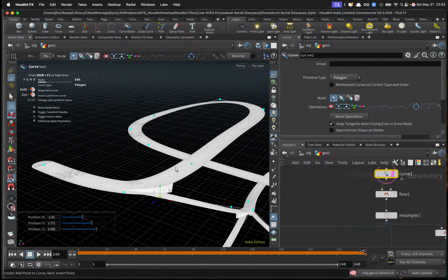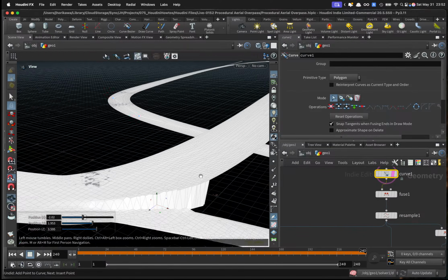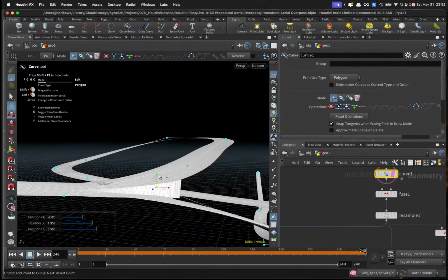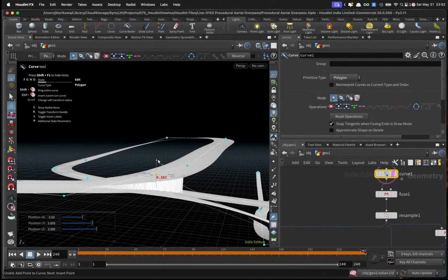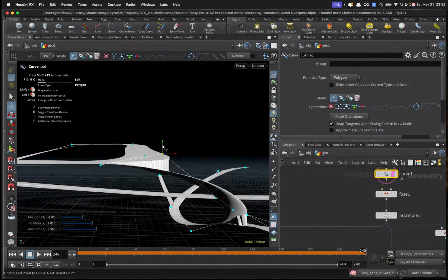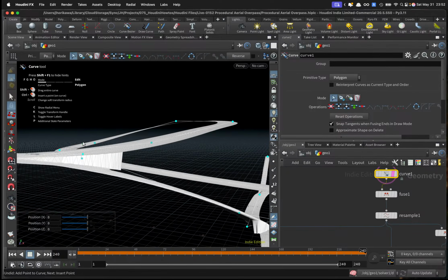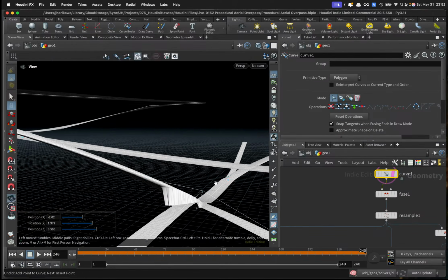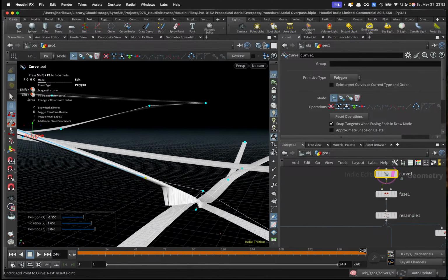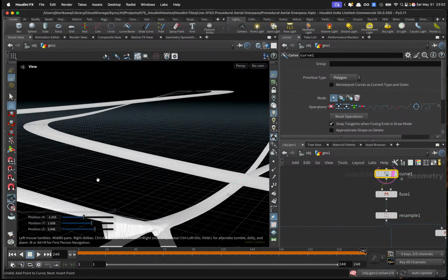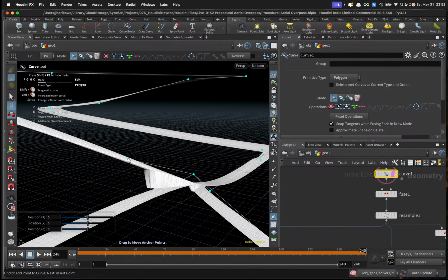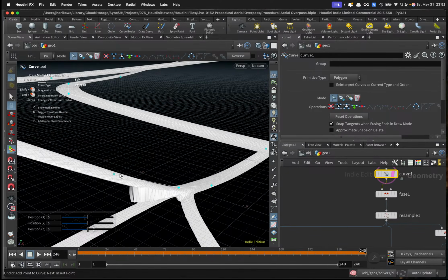Move this a little bit upward so that the initial connections of the two roads will be flatter. Let's remove the snapping and, okay, well, you might want to add additional points to this. So for this one as well, let's move this underneath, going downward. Let's select here.